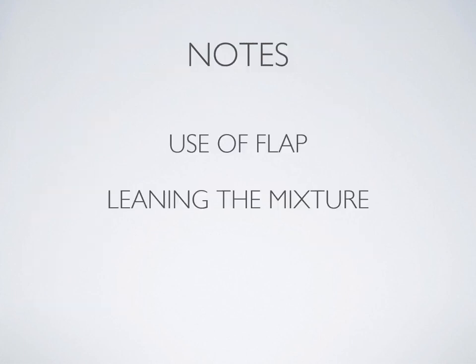Just some really quick notes. I want to talk about the use of flap because yes, even though flap can give you more lift, they actually give you way more drag as a result. So in your situation where you want to stay up in the air for as long as possible or even get the best range, you never want to use flap because they're really just increasing and adding additional drag on your airplane. Also, we're going to talk about leaning in the airplane. We're going to talk about how you lean and why you want to increase your mixture as you go into a descent or an approach for landing.